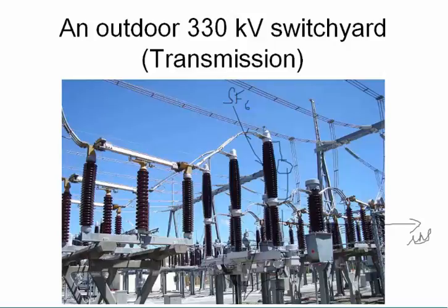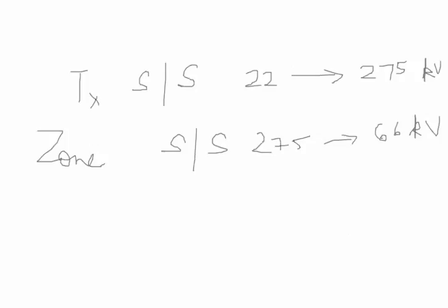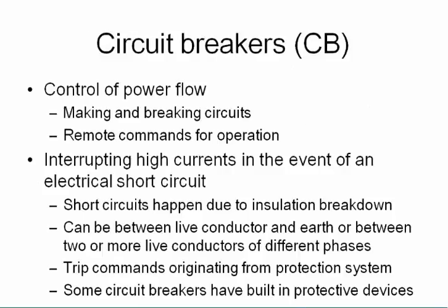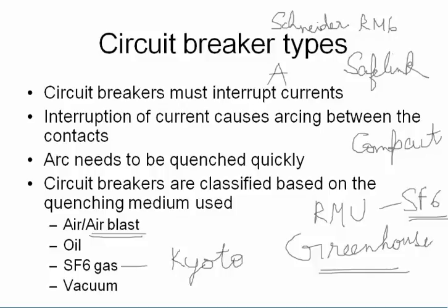And in terms of switchgear, if you actually Google Schneider RM6, I'll just write it down for the benefit of people. If you Google Schneider RM6 or ABB SafeLink, that shows you ring switches insulated with SF6. So you can have a look.